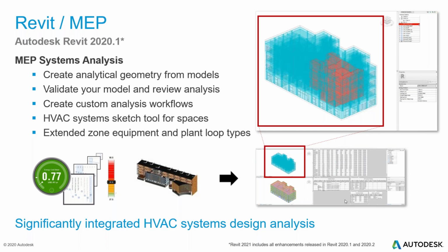You can have a complete summary of the energy efficiency of your building as soon as you follow the correct steps in your design: assigning spaces, rooms, assigning the quantity of energy for heating and cooling, and then you will be able to have a very interesting analysis and analysis reports in Revit.